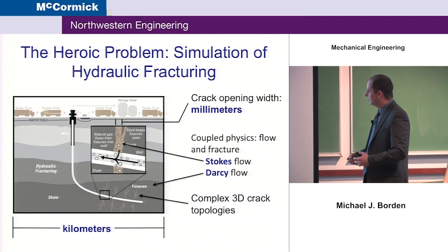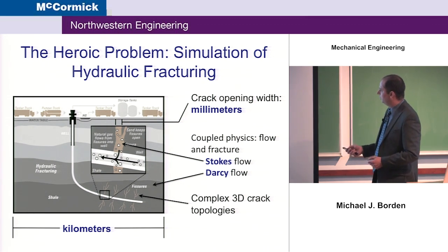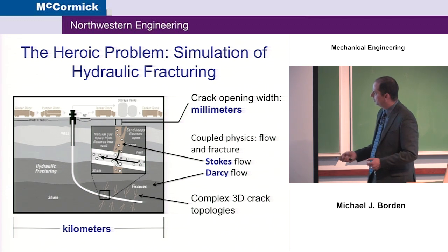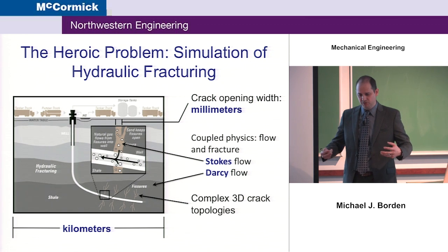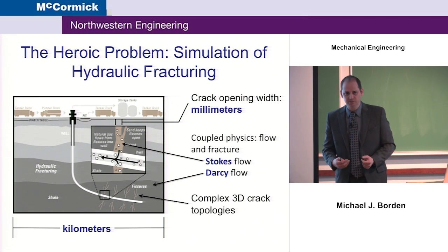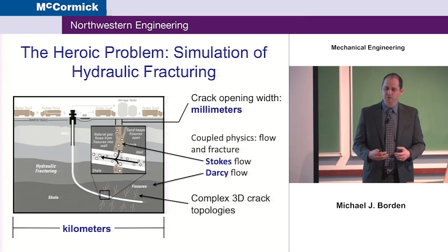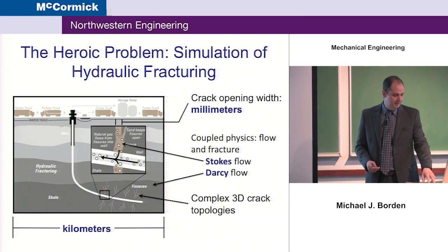There's also the complexity of the physics. We couple our flow with our fracture. Out in the unfractured area, there's this Darcy flow regime that must transfer in a consistent way into Stokes flow inside the channel. So there's a coupling between the fracture and crack growth and the fluid, and also the transition of the fluid flow from one regime to another.